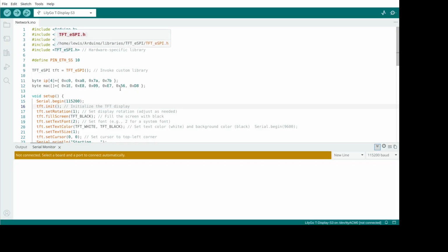And then you'll have Wire.h, which allows the serial output, so you will get the text out of this thing down here. If you don't have one that has a display on it, you can still plug it into a computer and get the information. And then you'll have TFT_eSPI.h, and that one is a hardware library for the LilyGo T-Display.